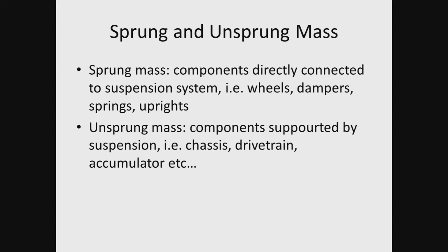And so if you were to go over a bump on the front left wheel and it shifts that wheel upwards, there's a period of time in which all the components have to move through the cycle, and the heavier they are, the longer this takes, and thus the slower the response of your suspension system. Whereas you want your suspension response to be as quick as possible to changes in the road surface to accurately absorb any of the forces coming through and keep your car nice and stable.